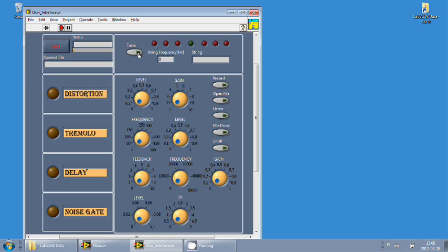The first effect I want to present is located on the bottom of the screen and is called noise gate. It cuts the output signal after reaching specified conditions. The level knob represents the level of magnitude under which the gate will cut the signal. dt represents the time after which the gate will take effect. Now I will set some parameters and demonstrate the working of the gate.